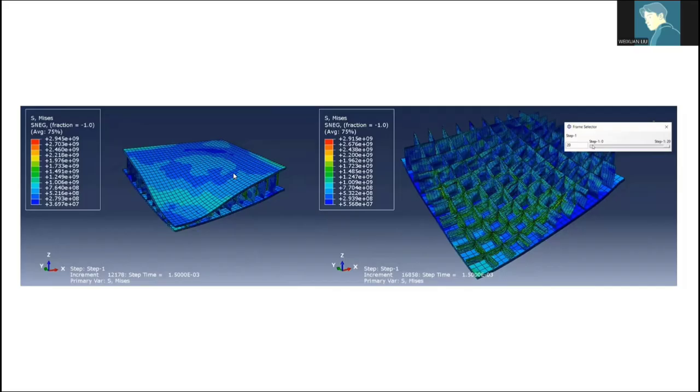Okay. Since the calculation took so long, I finished the calculation and put the result here. So, with the TNT air blast, the sandwich structure will behave like this. The form like this. And if you remove the face sheet, you can see the core actually crushing like this. Great. But this is explicit dynamics. It's less trustworthy, but it's under a high strain rate domain, so it's almost the only way that we could calculate this problem.